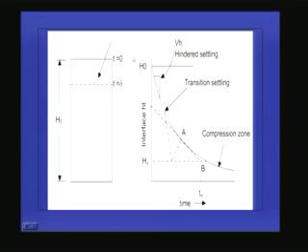Now, if we have the settling column analysis data, because we will do the experiment with a particular concentration, finally we will get a curve something like this, with an initial portion, and this is the portion where the compression is taking place, and it becomes asymptotic to the x-axis. So, what we have to do is draw tangents to this straight line portion and this asymptotic portion.